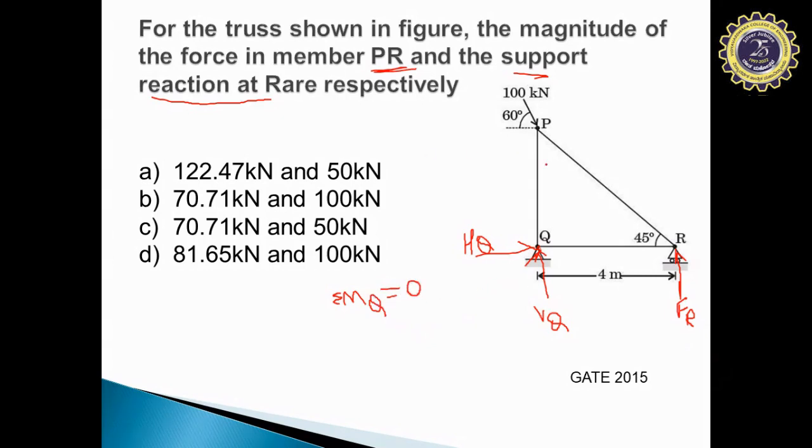In order for this to apply, we need to resolve this force into two categories. To resolve, the best method, if you still have confusion about the direction, is to go to the back end of the arrow, draw a plus mark, and see where the arrow is going. The arrow is in between these two parts. So that clearly indicates that the resolved forces will have these two directions.